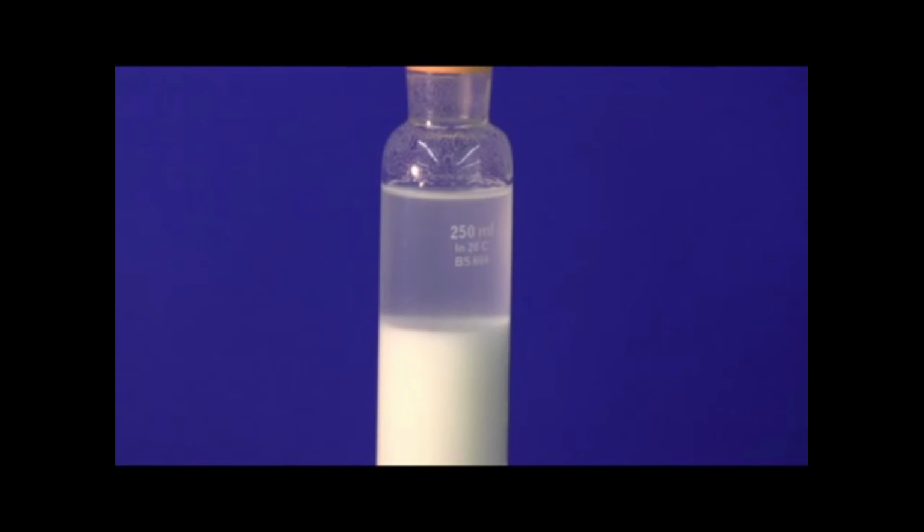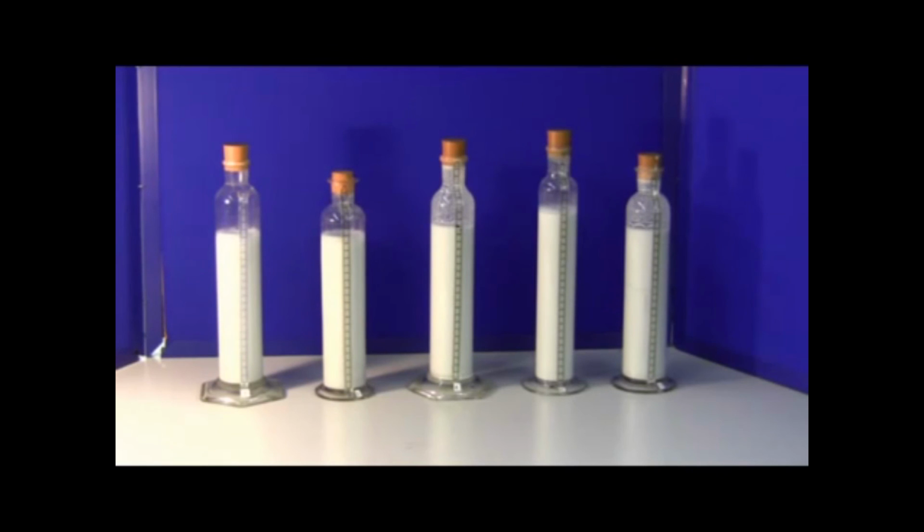And this is an unusually fast sedimenting system. Most things settle much slower than this. Sedimentation is very much liked because it's cheap, it's gravity driven, so the energy requirements are very minimal, and you can see that the interface is now just coming below the gradations on the measuring cylinder, and it's pretty much going to finish somewhere around there. So that was a very high concentration. If we had that much lower concentration, it would have settled much faster.